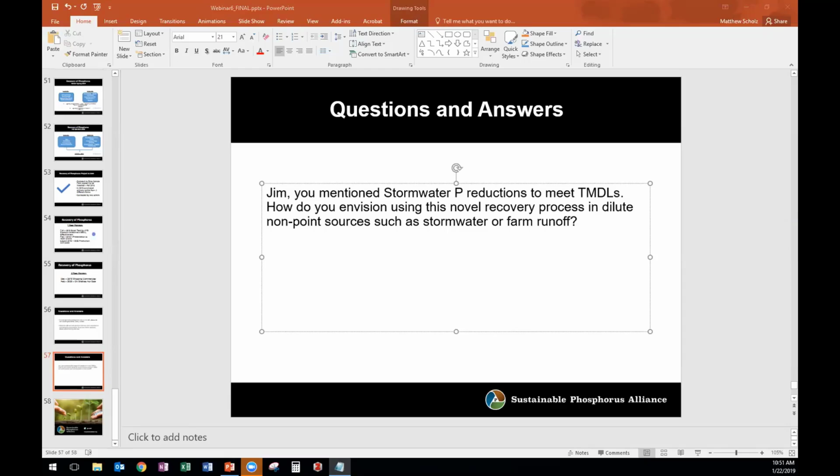By meeting the 0.2, besides finding that 40% increase in recycle, we're also finding our land application program, which involves a farm partner right here near the facility, has higher numbers of soluble P, which we would expect.